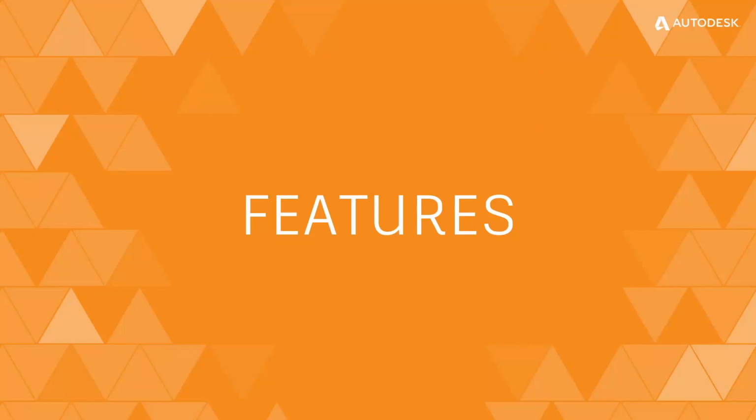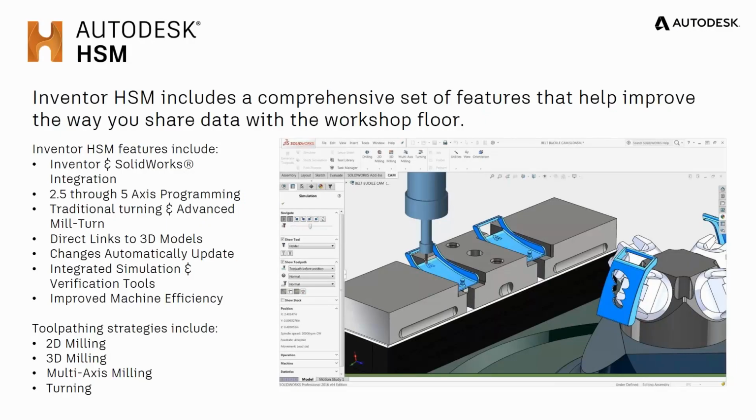So let's have a look now at some of the key features around why you should use Autodesk HSM. We've already touched on some of those before. HSM is a comprehensive set of features that enable you to share and leverage that data on the workshop floor. It integrates with inside of both Inventor and SolidWorks and enables you to run toolpathing for a number of different machining strategies from 2.5 axis right through to 5 axis simultaneous machining, as well as traditional turning, as well as mill turn configurations as well.